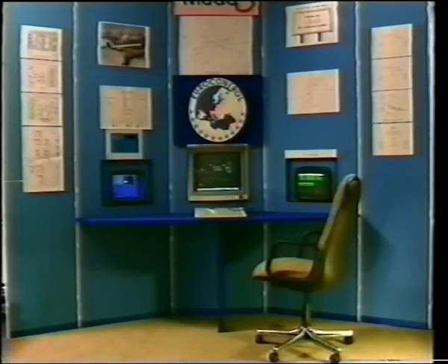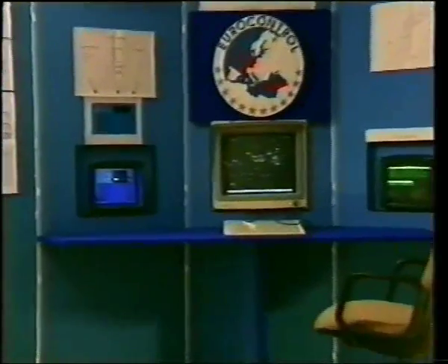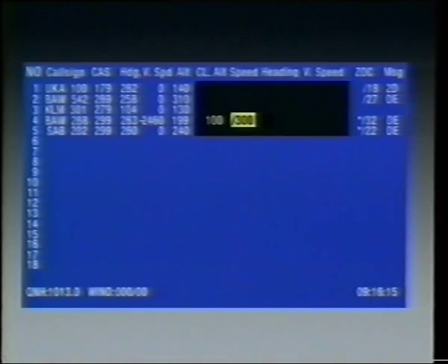The workstation consists of a centrally mounted medium-resolution color terminal that presents the radar picture. To the left can be seen the data link ground terminal display. This electronic data display provides the controller with an aide-memoire. In addition to indicating when the clearance has been confirmed, this confirmation is also shown by the removal of a yellow overlay that indicates the receipt of the message in the aircraft and that the autopilot setting matches that clearance. If it doesn't, then the clearance remains highlighted in yellow.